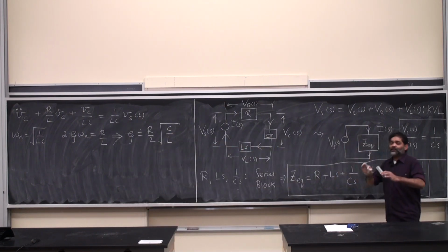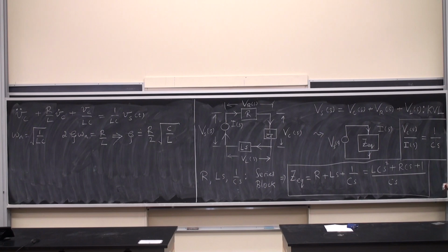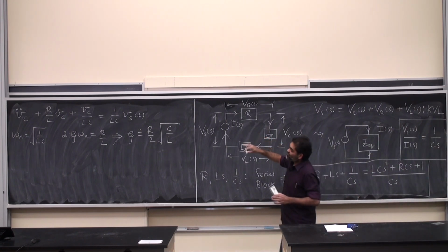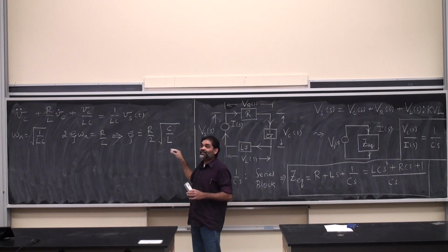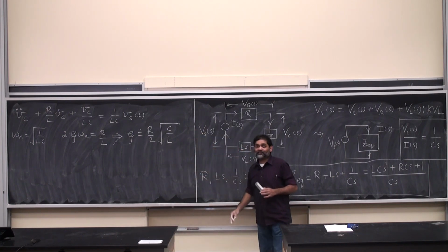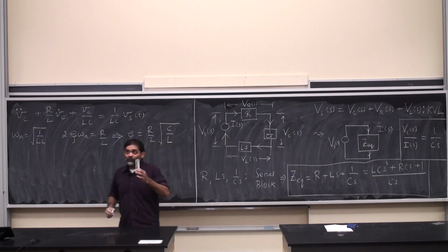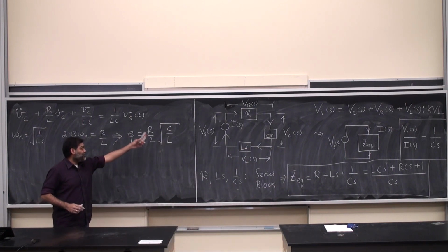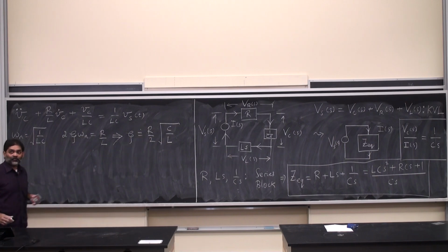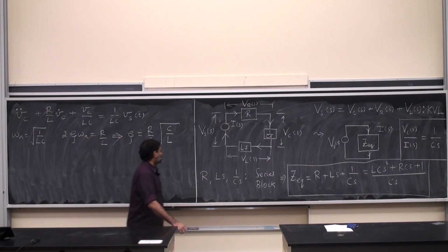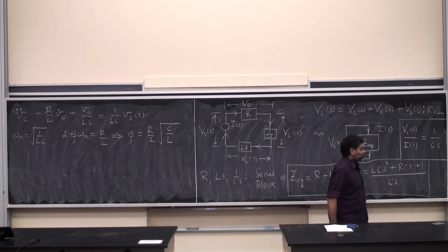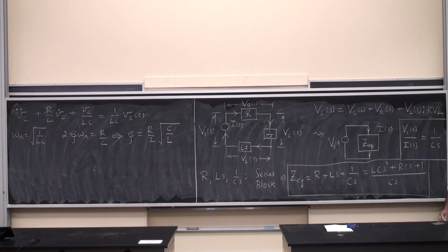And if you are really picky, an interesting exercise is to substitute for all the units of R, C and L. L is in Henry, C is in farads, R is in ohms. Bring it back to the basic units. And then you will figure out that zeta does not have any units, it's dimensionless. And obviously you'll end up getting this to be 1 by seconds, frequency.